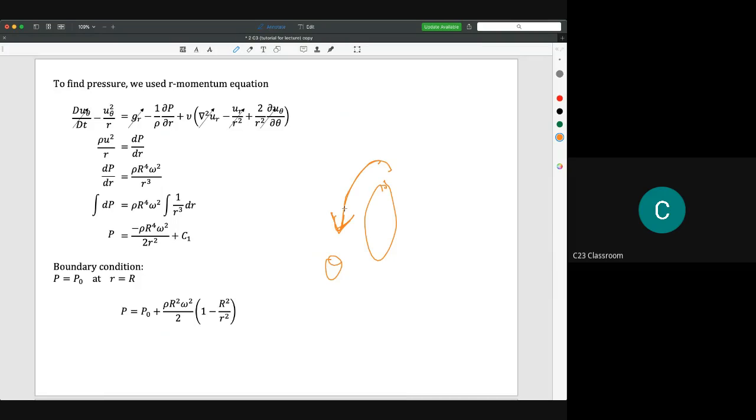According to our condition, we are discussing that the velocity is steady. Steady means the velocity is not changing along time. So the velocity on the same streamline will not change. The molecule here and the molecule here are not changing, they are constant, they have the same value. You know that in the Bernoulli equation, when the velocity is constant, the pressure is constant.